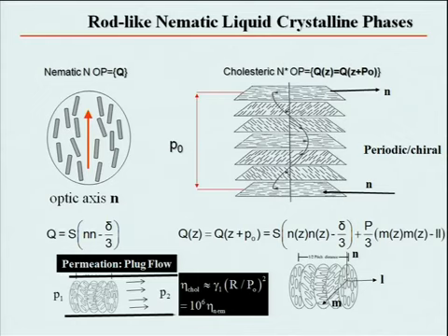And in fact, sometime in the 90s, I forgot to put the reference here, I worked out the structure. You can cast this permeation flow problem as a Darcy law problem. So that's why you pick up this factor here. The velocity is a plug flow velocity. This velocity that results from this pressure drop can be expressed as proportional to the pressure gradient, and this Darcy coefficient, if you will, scales with the wave vector squared.